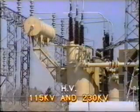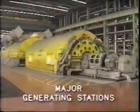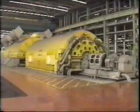This allows at least one end of each high voltage line to be monitored. Also, every major generating station, and every station with interconnections to other systems. Normally, oscillographs are not located at the distribution substations, except those installed to analyze special problems or to conduct research.